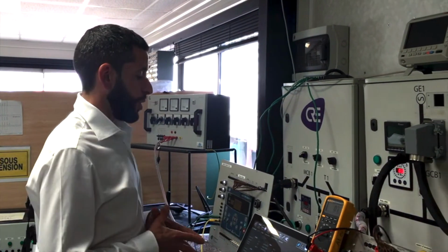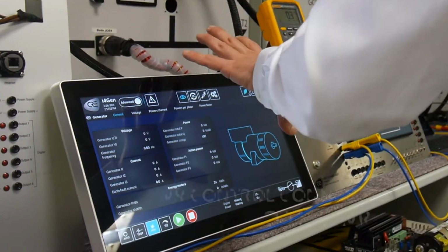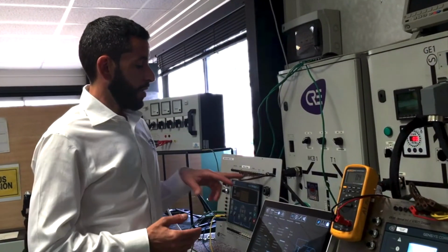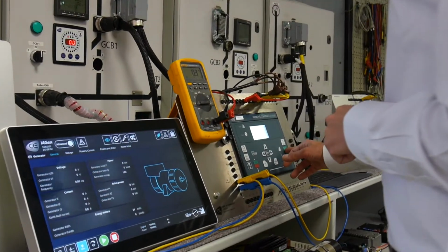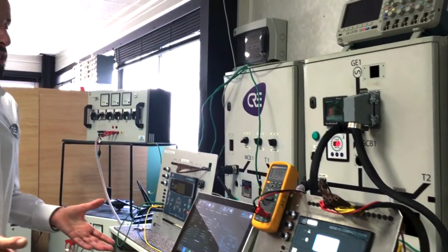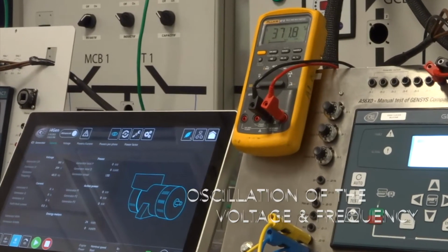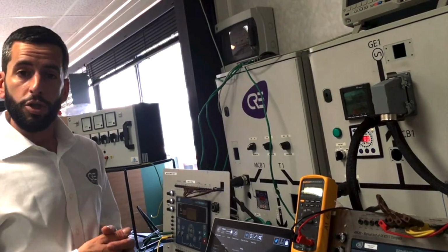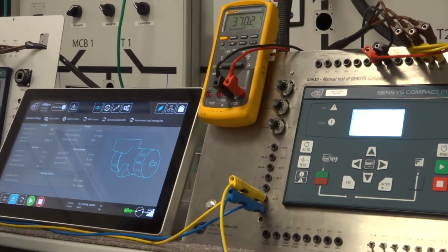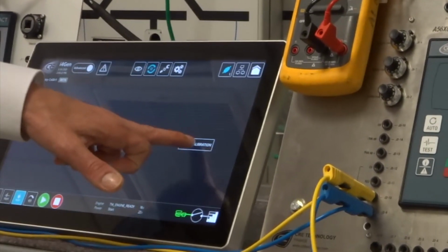So we are assuming now that we are connected on the genset. Speed control connected to the governor, AVR control connected to the AVR. So I will start up the genset in manual mode and launch EasyCalib with the dynamic configuration menu. So genset is started up. I can see that my voltage and my frequency are not correct at the moment, and I have no oscillation of the frequency. So we will launch EasyCalib and let's see if it can inform us about something. I go in dynamic configuration, then start EasyCalib, start calibration.